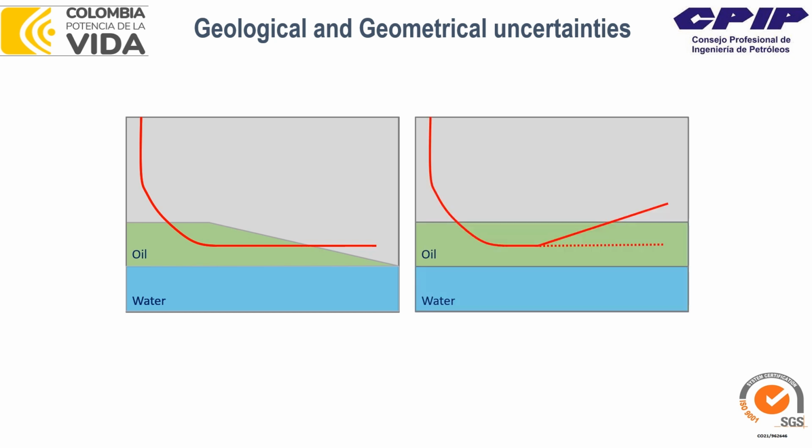Or maybe the top is where it was, and you were drilling slightly up without noticing, as I told you in the previous example. So you see 90, 90, 90 degrees at every survey, and then you hit the top. That's because of the geometrical uncertainties based on the survey error and the survey method calculation. That's the current limitation of the technologies we are working with right now.